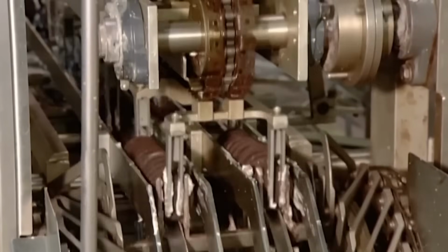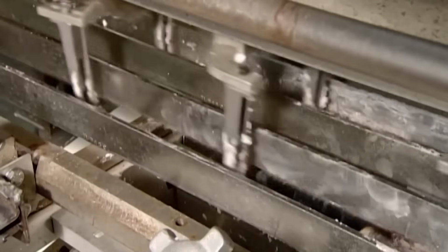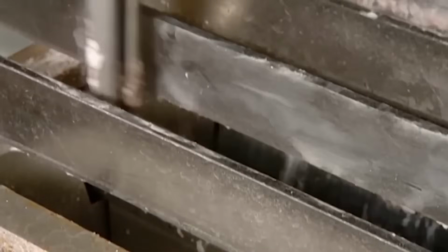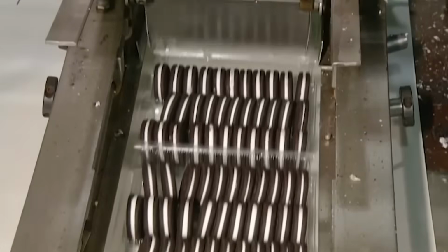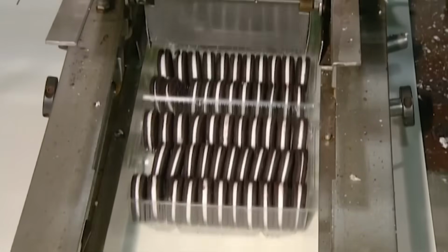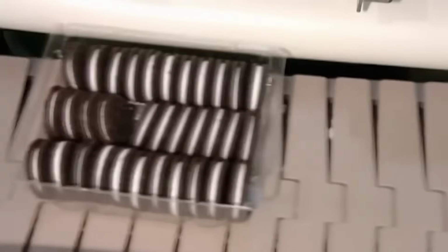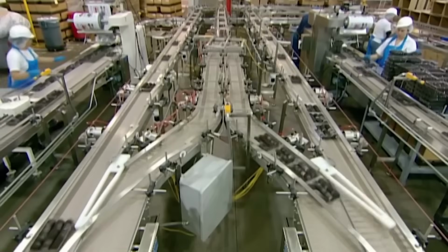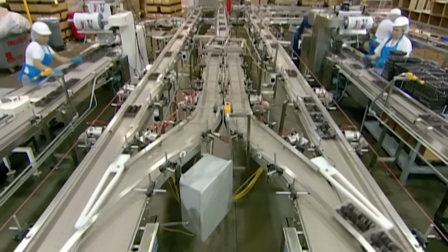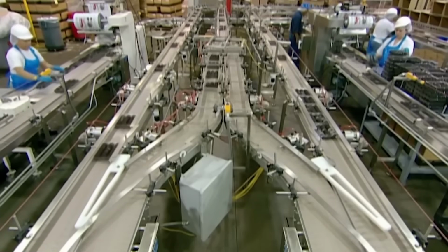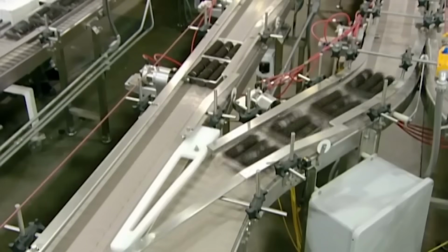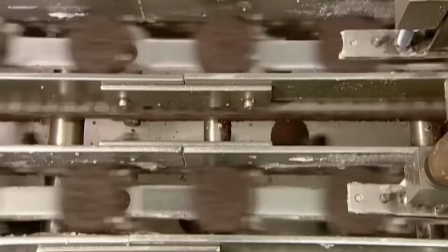As cookies exit the cooling tunnel, they are directed toward the packaging line. Here, the cookies are grouped and arranged into stacks or rows depending on the intended package format, whether it's a classic tray-style retail pack, a resealable pouch, a single-serving sleeve, or a multi-pack unit. For traditional packs, the cookies are guided into channels that group them into stacks, typically of 3 or more, which are then lowered into thermoformed plastic trays by robotic pick-and-place units.